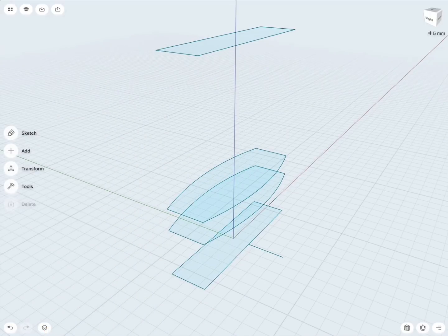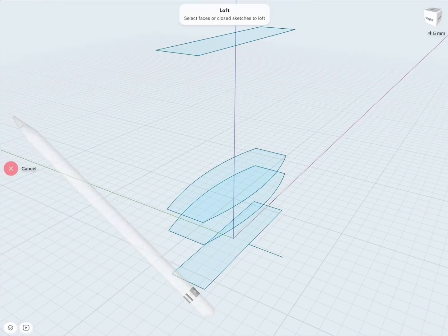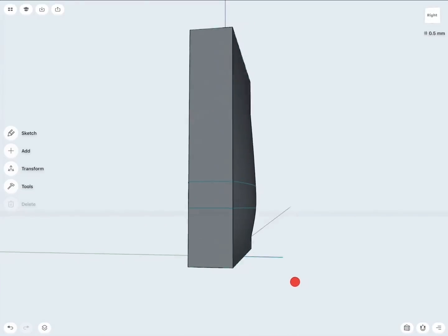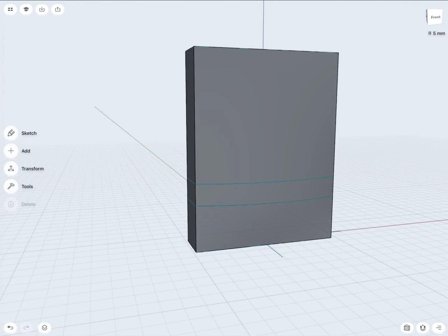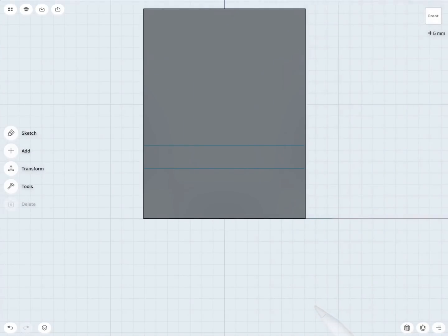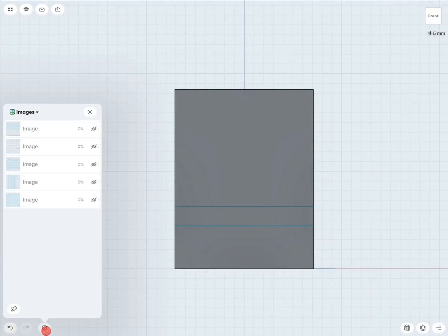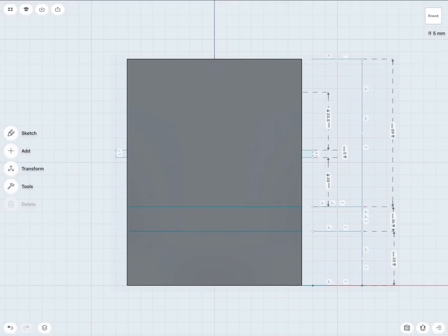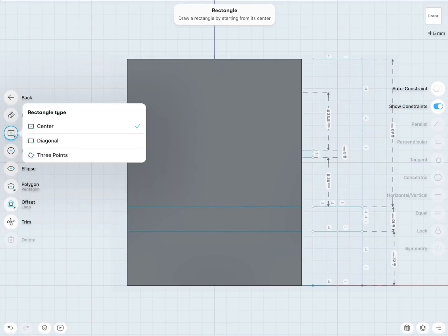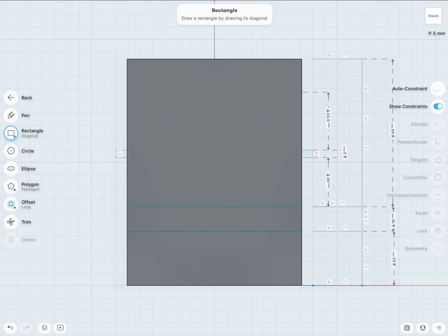So now we can do the same via the loft. So there, there, there, and there. And there we are. Nicely bellied out. We would like to do that cut to separate these two parts. I go to the front view. I will turn this sketch on so I see where the stuff is. So I can create a rectangle.